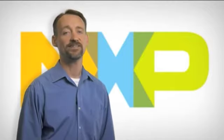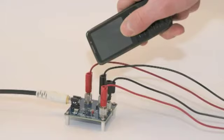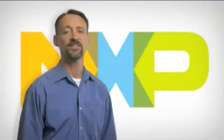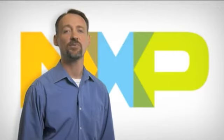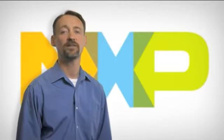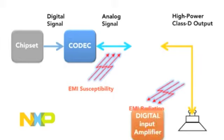I think many can predict the sound that the analog system will make. This sound, sometimes called GSM noise, or bumblebee noise, is caused by the RF interference being picked up on the input trace of the amplifier and being amplified with the rest of the signal. By switching to a digital amplifier, you eliminate that pickup.